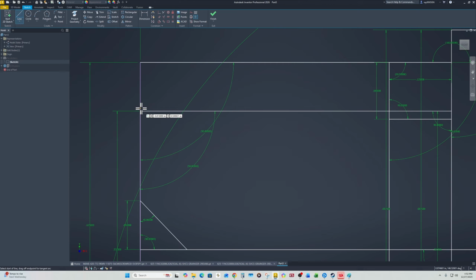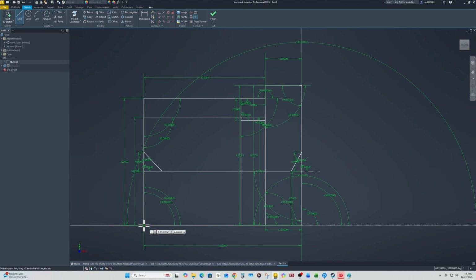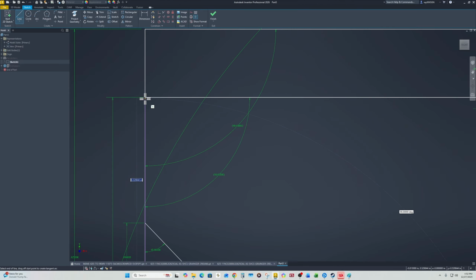So cool. Let's just see how much difference it is from here to here. I was gonna say let's give it a certain diameter, so yeah, just give it a certain diameter. So I'm gonna choose this line again right here. It's 1.25 or 1.063, so I can just give it 1 inch. So 0.5, tab 9, tab enter.